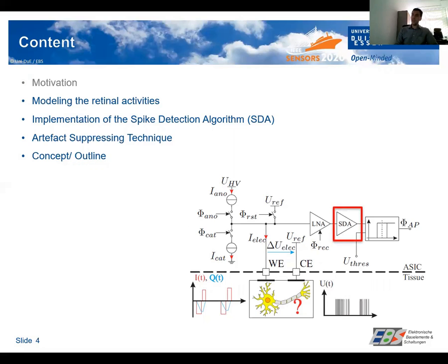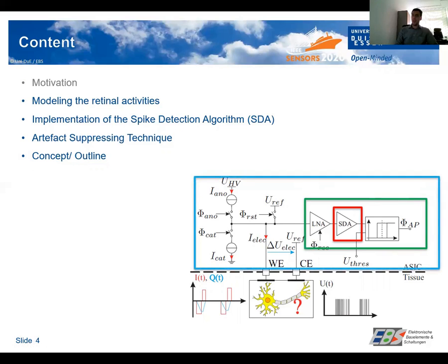the SDA, and with simulation results, I want to verify the complete recording module, which consists of a low noise preamplifier and a comparator. After that, I want to show you how it is possible to record and stimulate the tissue simultaneously without any artifacts due to the stimulation.